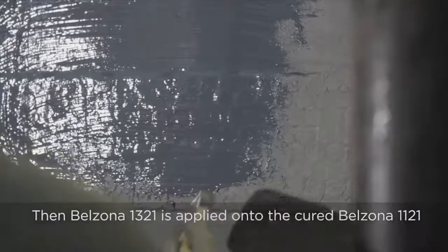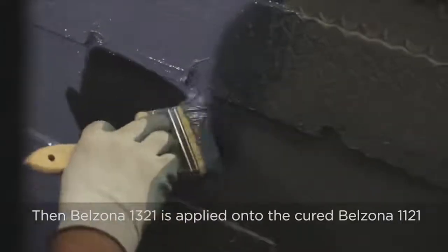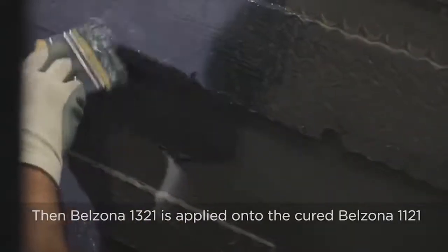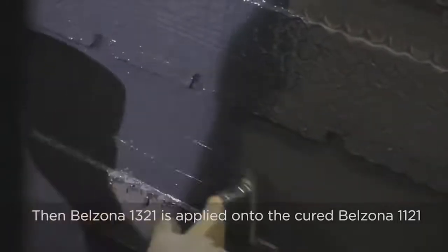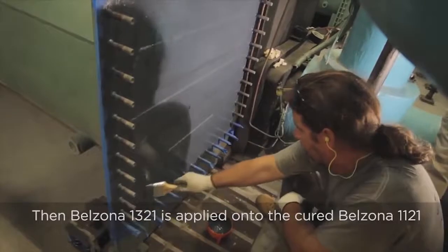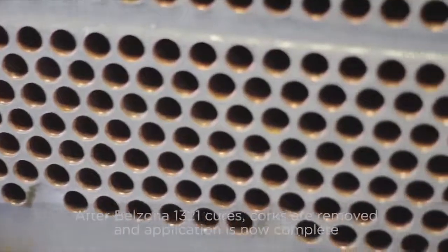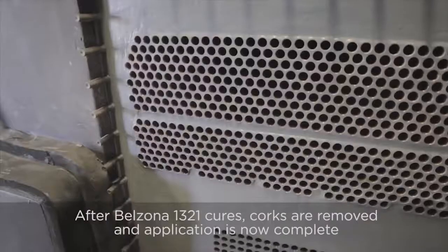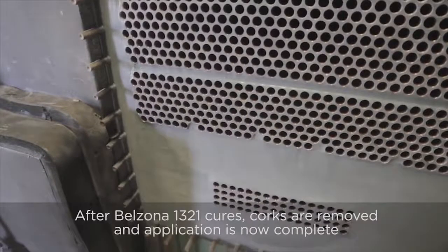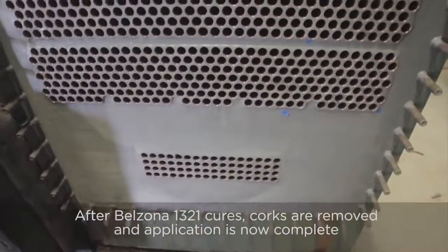They used Belzona 1121 in this example because it had an extended working life and also an extended overcoating window, which meant they had plenty of time to apply this material on top. Once both of them have cured, you can then remove the corks finally from the system and dress back the coating to give you a nice flush finish where you've prevented the liquid from contacting the surface, and you've also isolated the tubes from the tube sheet face, which means you've prevented any type of corrosion from happening in the future.